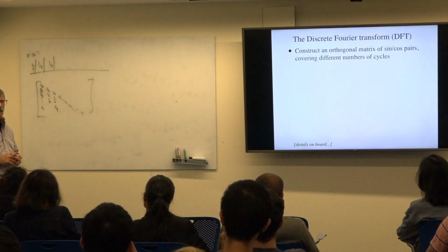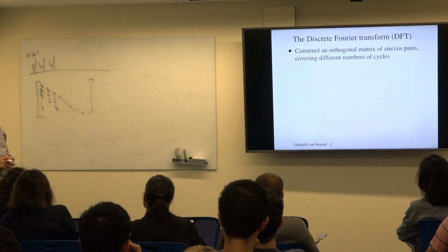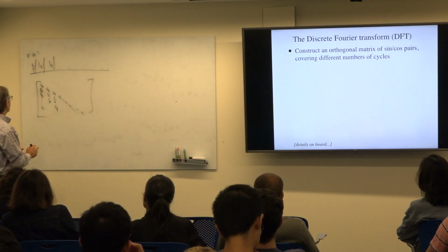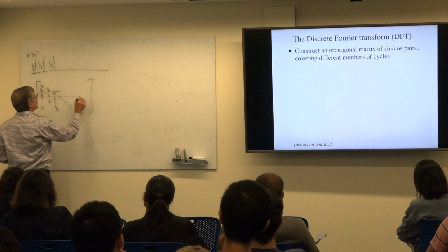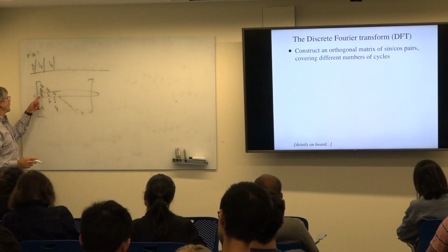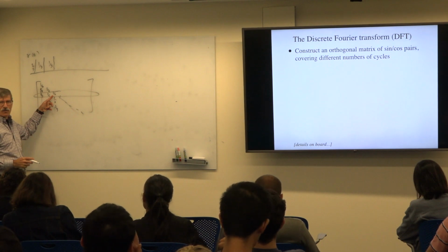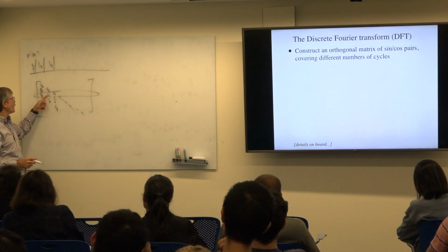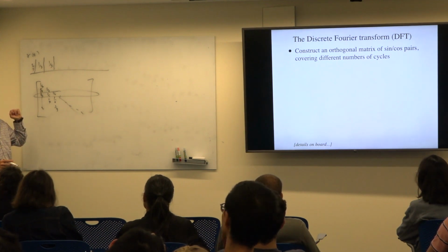But let's think later on, where we're not dealing with edge effects. So for example, at time step 3, now we're going to look at rows because that's the output perspective. The output at time, let's count from time 0, 1, and 2. So the output at time 2 is 1/3 the input at time 2 plus 1/3 the input at time 1 plus 1/3 the input at time 0. What is that in English? It's an average of the last 3 time steps.